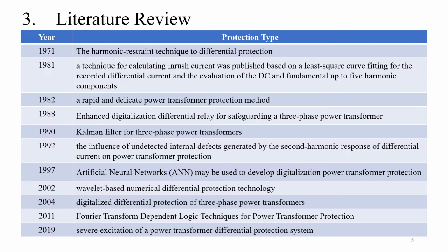The suggested restraining model with phase comparison percepts was tested in the protected zone using the MATLAB SIMULINK environment. The result shows that the likelihood of erroneous tripping during external fault length is reduced by over tenfold when compared to non-restraining methods and is as low as 2% in the most severe modes.